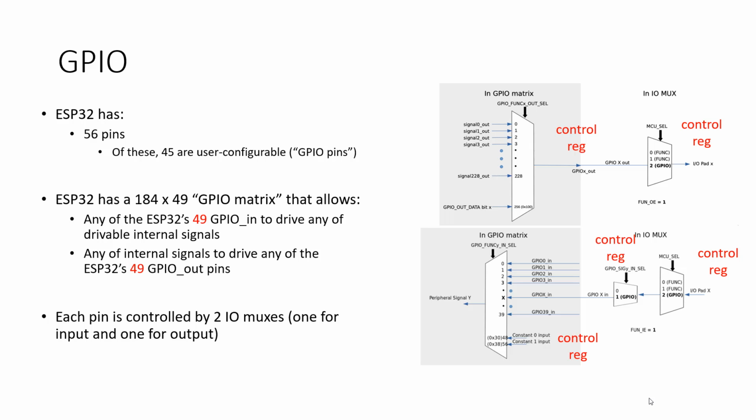Okay. Now the problem is that that alone is not enough, because there's also the secondary mux that the primary mux has to go through, and this is kind of a shortcut for high-speed peripherals. So each pin has an intended purpose that you could use to basically bypass this and connect it to one of its specialty purposes.